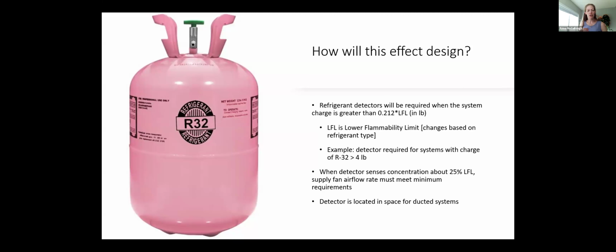If you are replacing your evaporator and your condenser and can still use those same line sets, I believe they will be required to be protected. As long as they are encased and enclosed and you cannot see them, you cannot run the risk of puncturing them and lighting a fire.